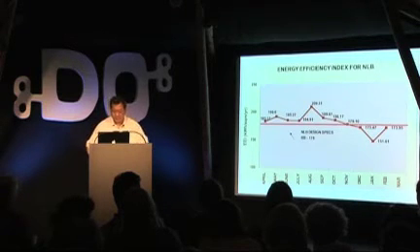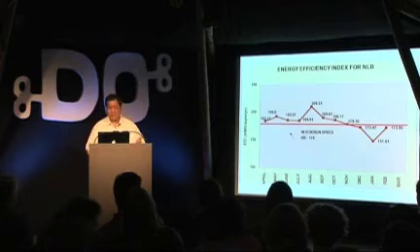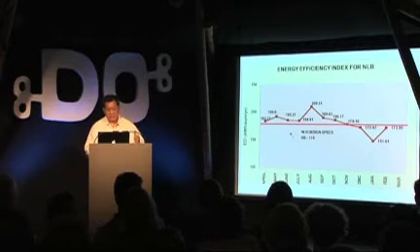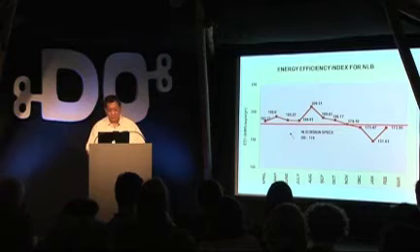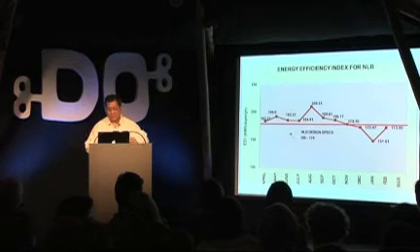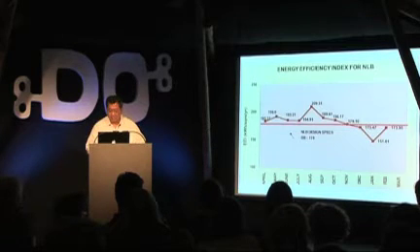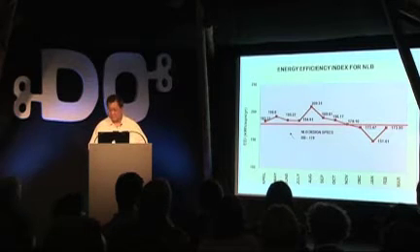You can see that the building was completed in April. And this is a post-occupancy evaluation of the building. Completed in April, you can see the energy consumption is high, from 183 to 196 kilowatt hours per square meter per annum. And by August, we reached about 209, which is incredibly high. Then the people started to use the building, and we started to learn how to use the systems in the building. And so by February, we got down to about 173.